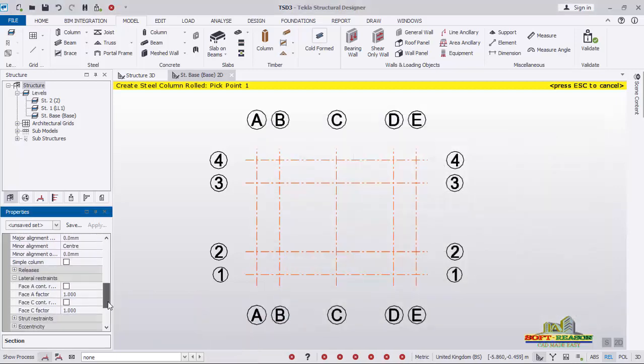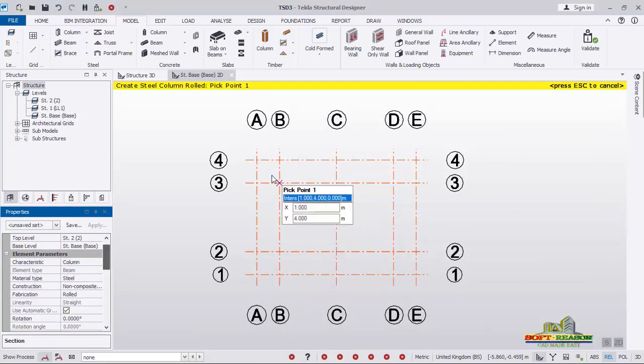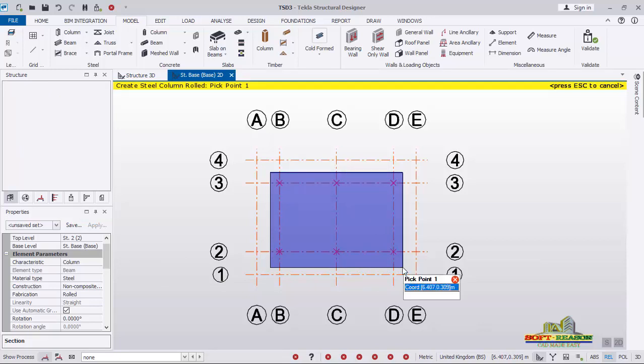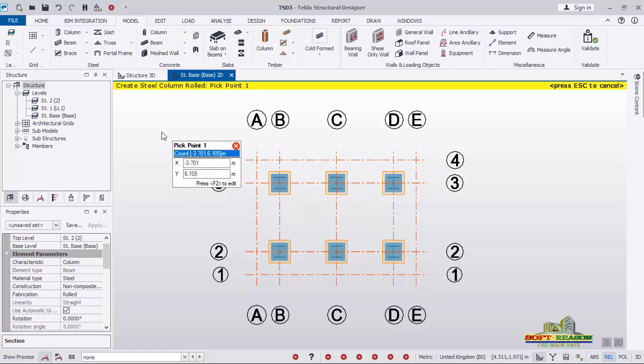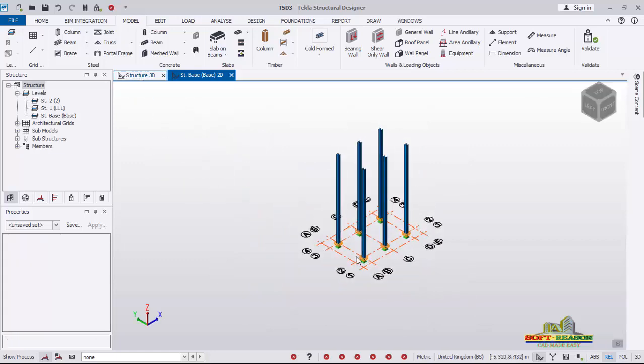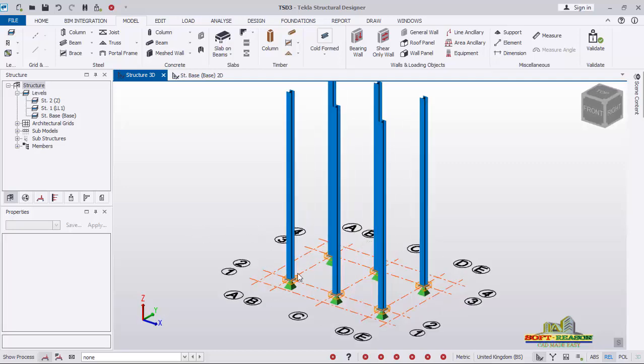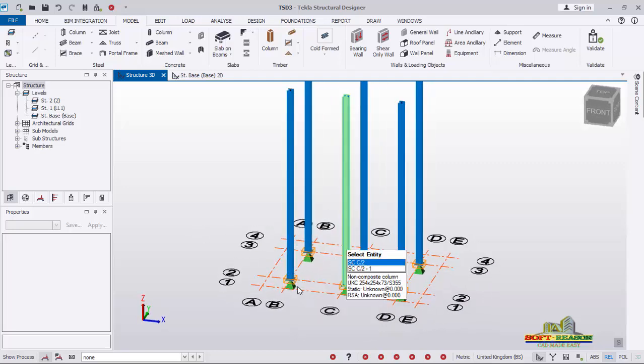So having that set successfully, I'll click this point and do a shift over this intersection. As those intersections have been highlighted successfully, I release my hand to insert the columns successfully. Straight away, I click on these provisions to have it in 3D, so I can see what I've done so far, which is this.